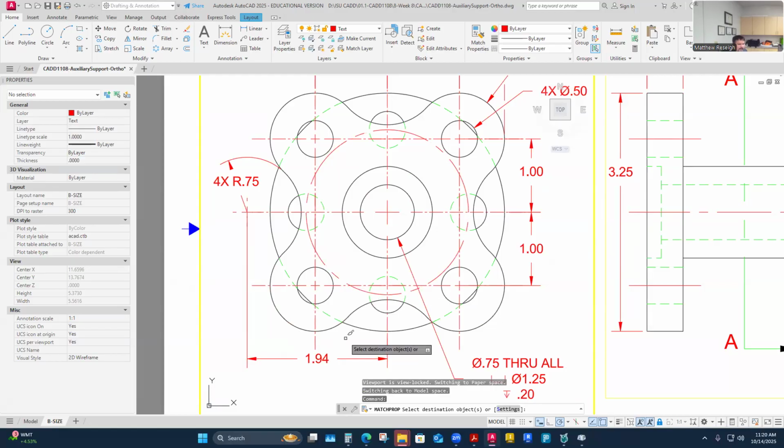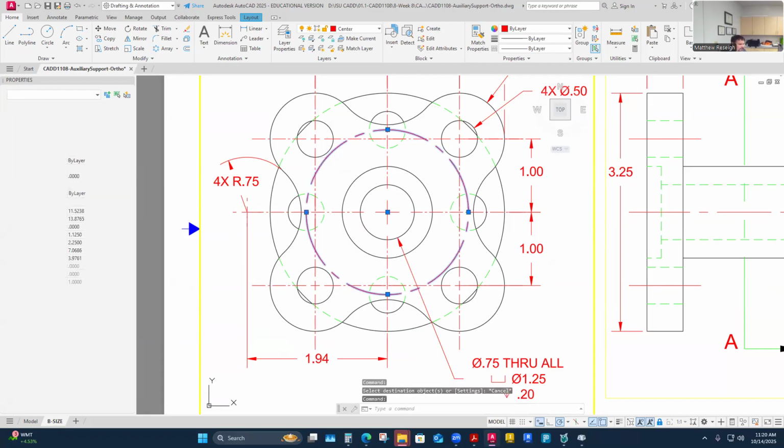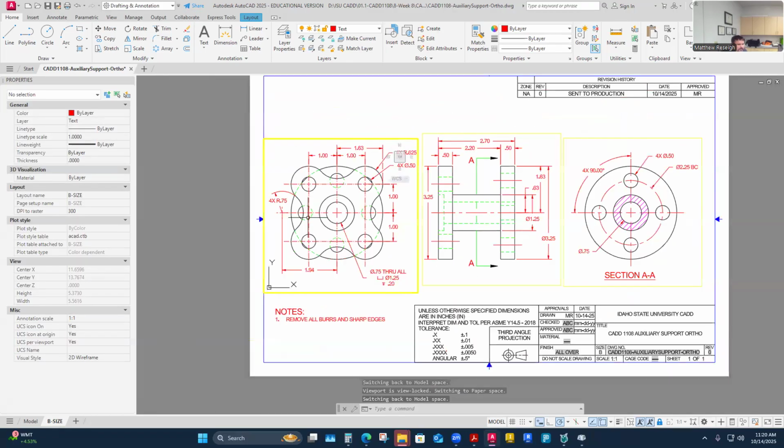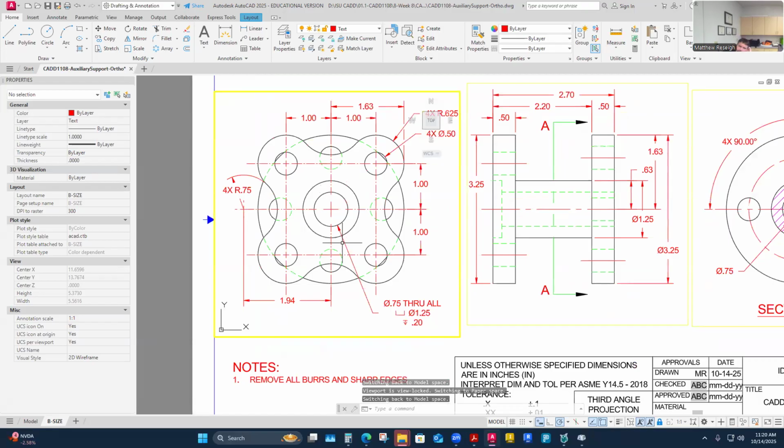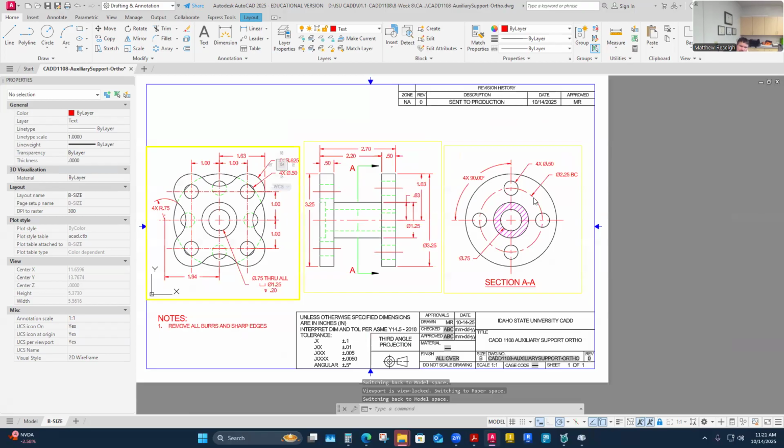I'm really not calling that out there. I think I'm going to delete this. I used rectangular coordinates here. That polar coordinate there just kind of gets confusing, or that polar center line. I carry that over here and actually call it out. So I'm just going to remove it from that view. I didn't notice that till I really got in here.